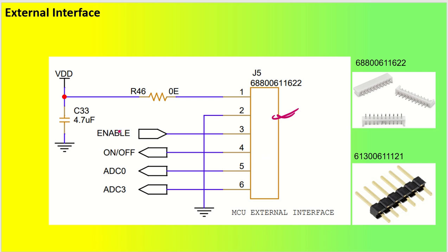So I have sent a signal from my microcontroller pin to enable that device, and I am getting output or feedback, so that whether it is on or off, that will be indicated to my microcontroller line. Okay, and there were two ADC lines that were coming from that board, so that will be utilized here. At the same time, you can see I have sent the same power supply from my microcontroller board to that device, so that device can be powered up through this particular power itself.